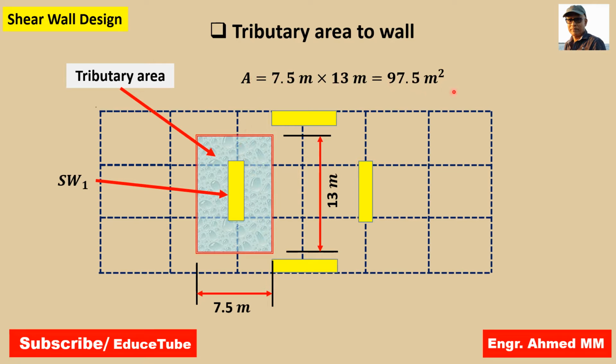So how do I get the tributary area? Already I showed in the previous slide. This bay, each bay is 6.5 here, 7.5 here, 6.5. So 7.5 from center to center. And here also, this is the center of this bay, so this part and this part give 6.5 and 6.5, so total is 13. And this length is 7.5 from center to center. If we multiply, we get 97.5 square meters. This is the tributary area to the wall.